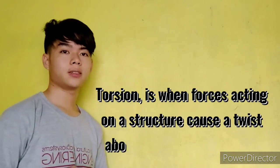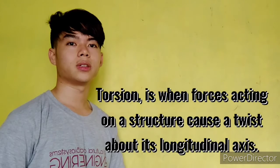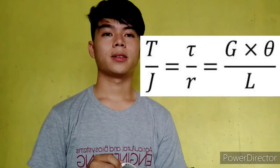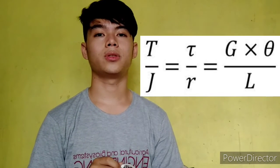Lastly, torsion. Torsion is when forces act on a structure to twist it about its longitudinal axis. For example, this is what happens in your spine when you twist your body from side to side. So this is the formula for solving torsion: T over J is equal to G times theta over L, where T is the torque, J is the polar moment of inertia, G is the shear modulus, and L is the length of the shaft.